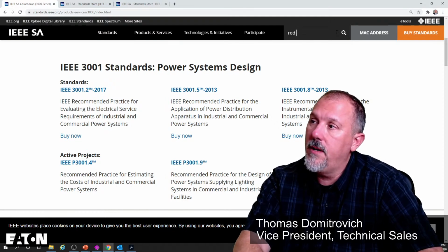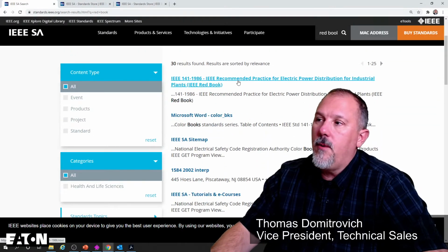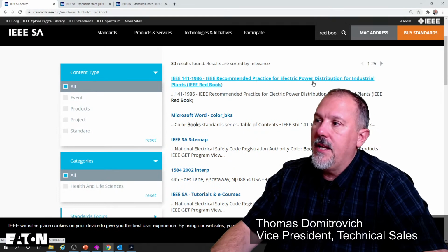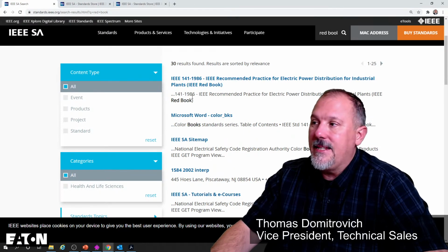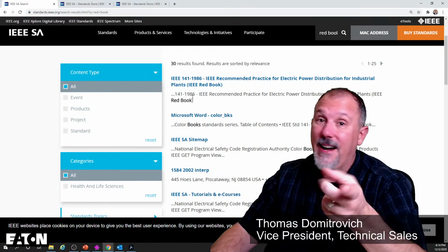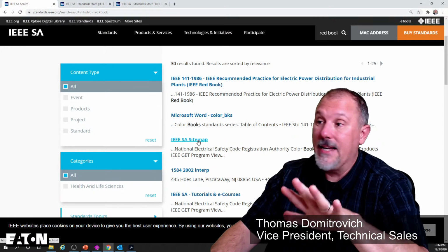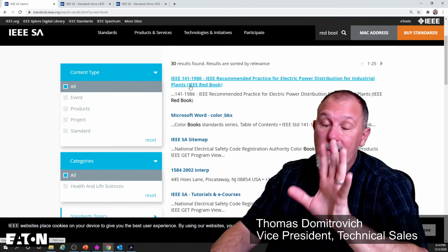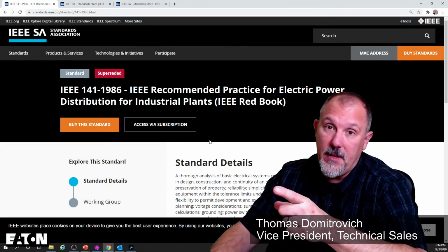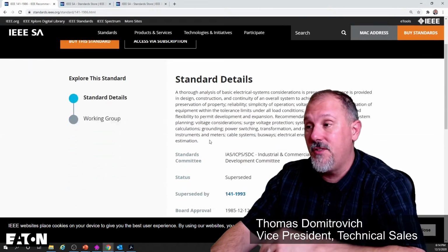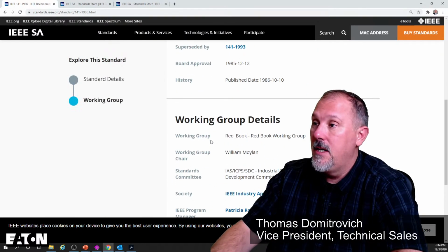We'll just look for the red book. IEEE 141. IEEE recommended practice for the electric power distribution for industrial power plants. That's the 1986 version. My personal opinion is I like the 1986 version better than the newer version. That's just my personal opinion, because they took some things out of IEEE 141 in the later versions that I found very, very handy.